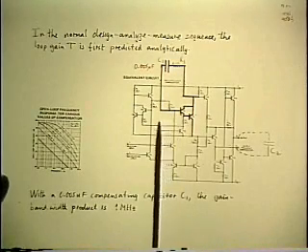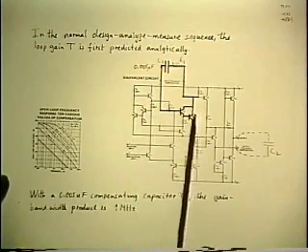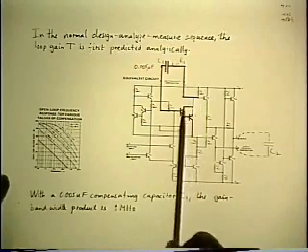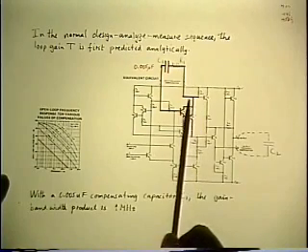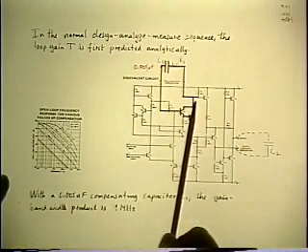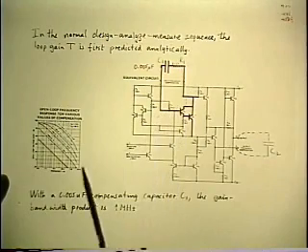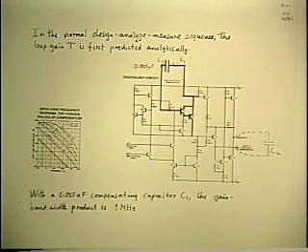So let's look at this simplified diagram. And you don't have to look very long to find out that there is one of the interstages here, which is a common emitter. Actually, it's a Darlington common emitter, but basically the same thing. And the compensating cap, which is outside, is actually a feedback cap between collector and base of a common emitter amplifier stage. And we spent a lot of time already discovering that the basic common emitter amplifier stage with a collector base capacitance has a right half plane 0.